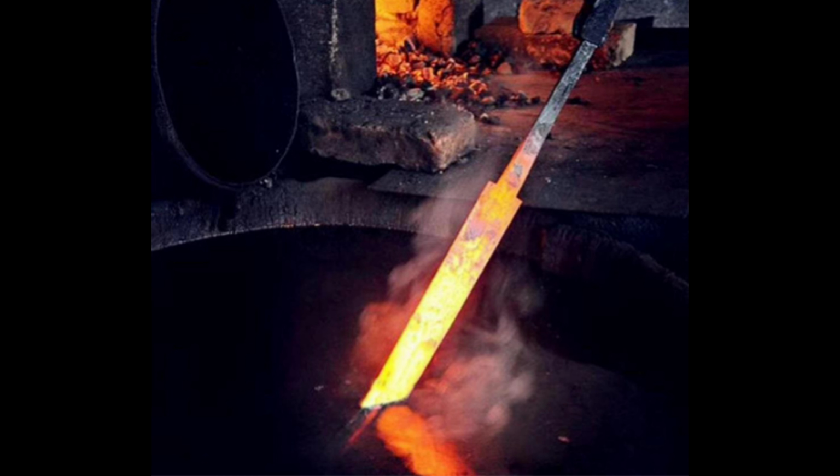So you have something called a supersaturated condition where there's more carbon in the lattice of the crystal than could be contained there under equilibrium cooling. If you allowed that steel to cool down very slowly, the carbon would come back out of solution. It's what it wants to do. It's its lowest energy state.